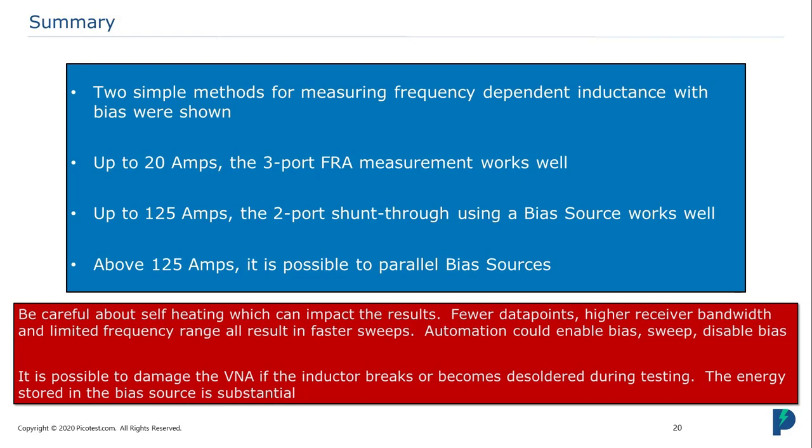One more warning is that it's possible to damage the VNA if the inductor breaks loose or becomes desoldered during testing, and so you want to be careful of that, and you also want to make sure that the inductor is soldered on the top of the mount board, not on the bottom, so it doesn't fall off if the solder does melt.